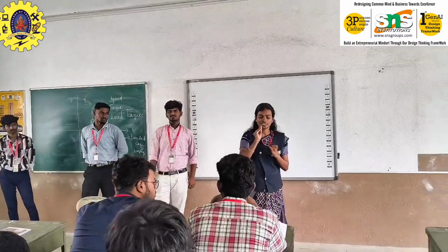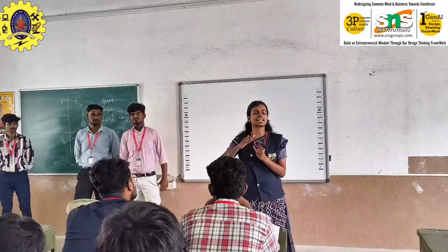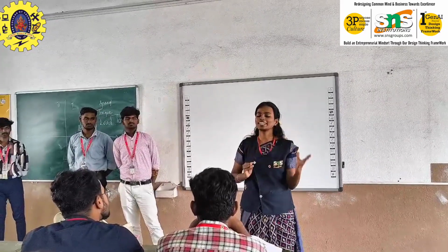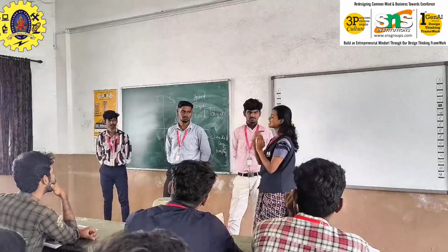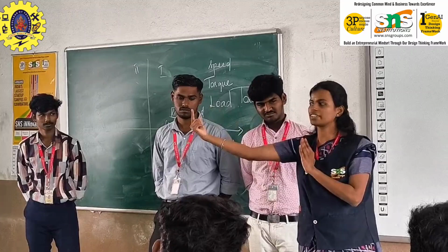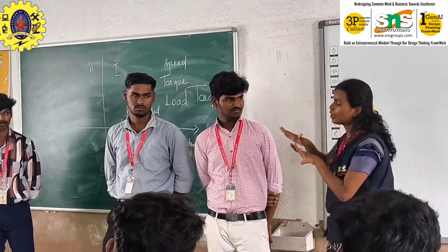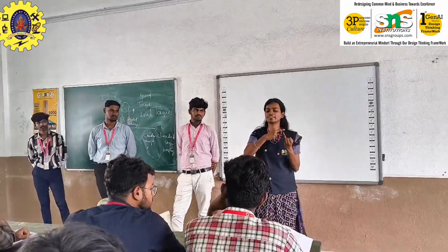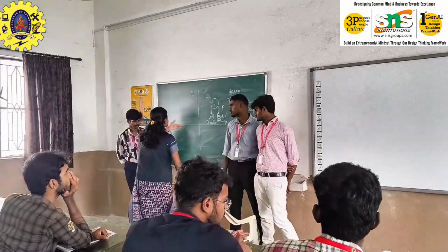Normally, know this: if the speed is rotating in the anti-clockwise direction, it will have a positive sign. If it is rotating in the clockwise direction, it is negative. So consider this as the anti-clockwise direction, when a person is rotating on this side. When they are rotating in this direction, it is clockwise. Normally in first quadrant operation, we have loaded weight and counterweight, and the direction of motion is in this direction.